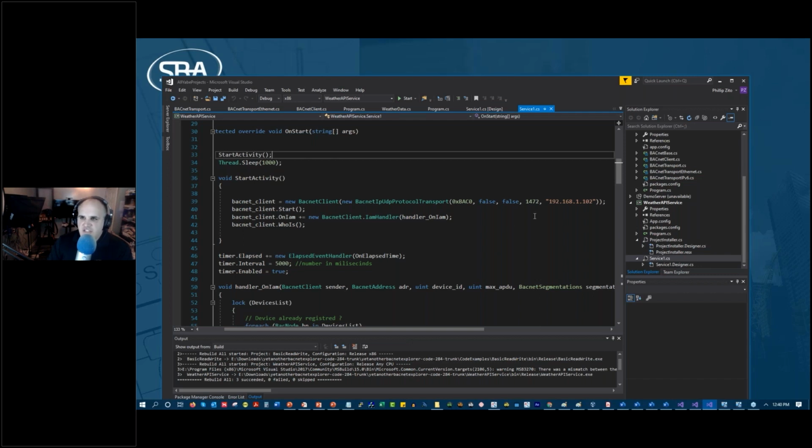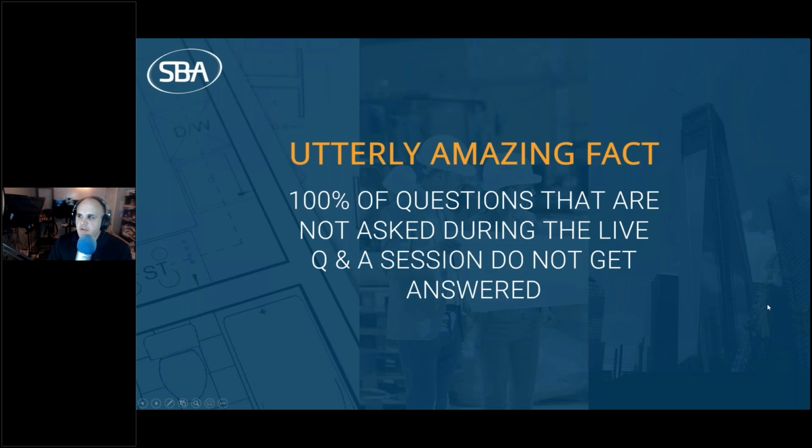That being said, if it is just a basic protocol integration, like what I was showing you, then you could run it through a JACE, or an Edge 10, any controller that has the capability to support the protocols. What you have to ask yourself is, do I want the data flow to go through a field controller? Do I want it through a supervisory device? What are my levels of separation? Do I want it to go from a server through a supervisory device to a field controller? What do I want to do? That's an architecture conversation.